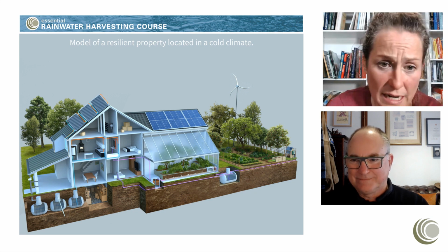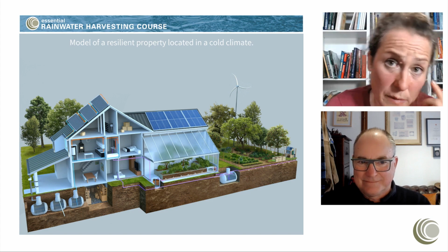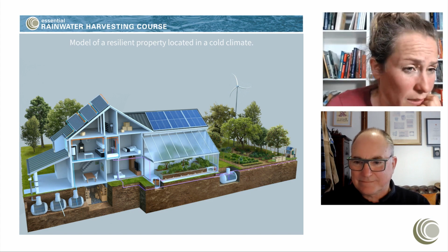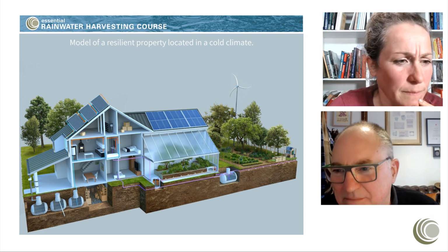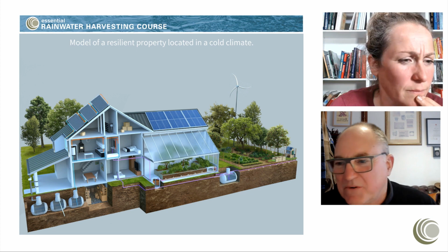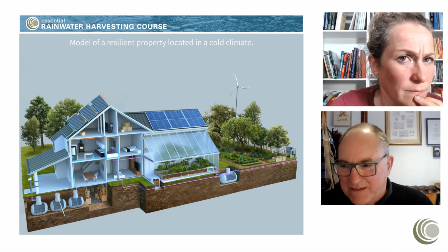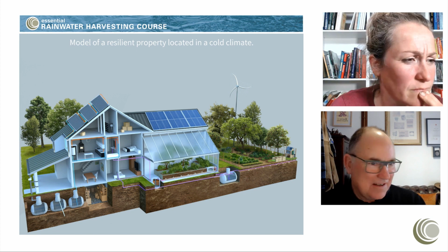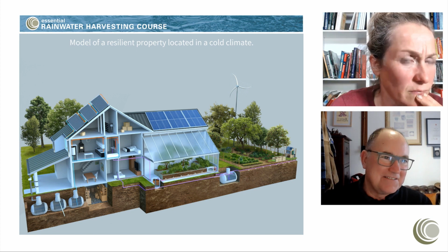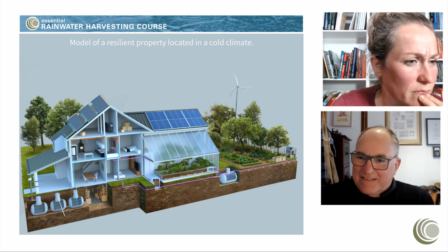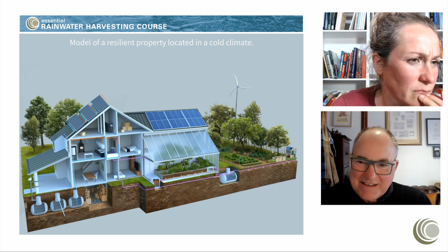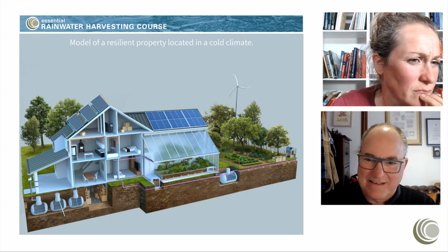This particular home has a greenhouse, and so there is a gray water system shown there. You've got a rainwater system, but you've also got a treatment train for the rainwater system because the water flows off the roof into the roof gutter system, which discharges via a leaf diverter into your rainwater storages, which produce treatment, and then as you can see, it's supplying through the house, and then that discarded water becomes the grey water, and it's supplying the other uses, including the plants.